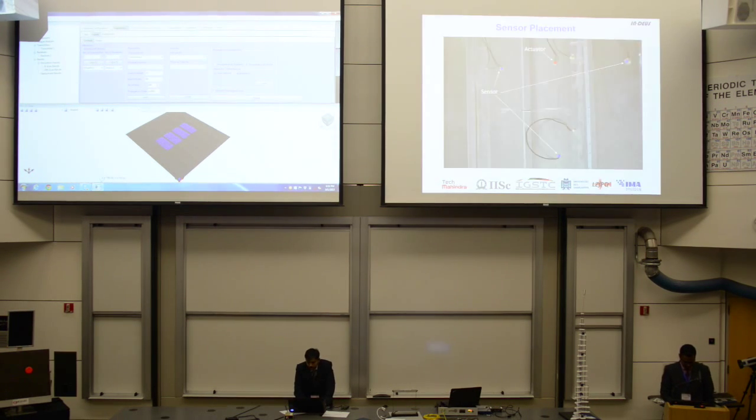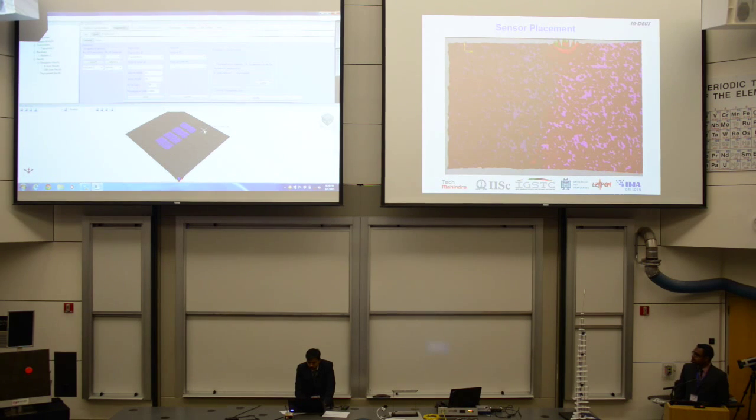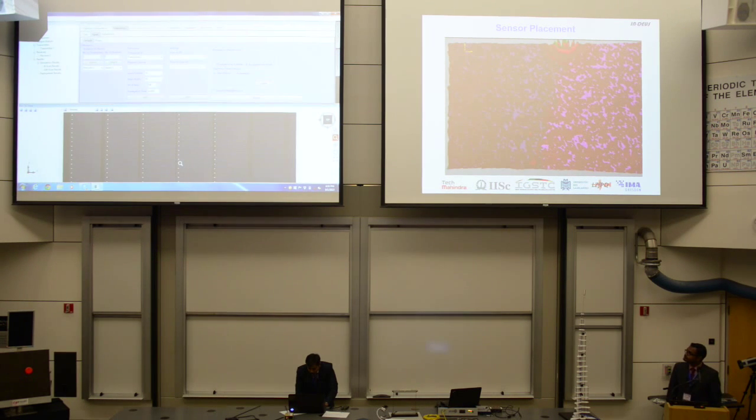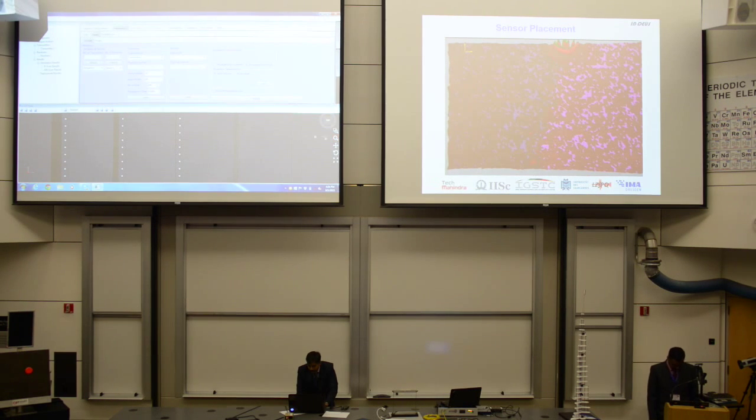So what you see here, we have loaded the finite element model of a stiffened metal panel, the schematic block diagram of which has been shown in our PPT. Here you see there is a blue region, which is the region I have selected for running our guided wave simulation. Just let me switch to the front view and I will zoom in on the selection region. So here you can see these are the rivet holes, and here is a crack present in the structure.